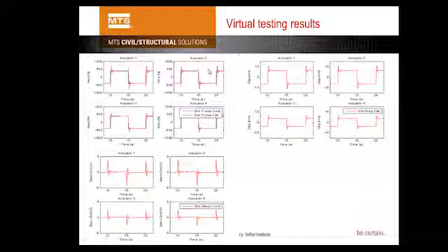then finally you reach the desired force level. Of course, in our virtual model, we can also output all the displacements on all the actuators and the servo valve command, which is used to drive all those actuators. Those are just some important signals that I'm outputting here, but essentially, using our virtual testing technique, you can output any signal inside your controller, and you can model those signals and output them as well.